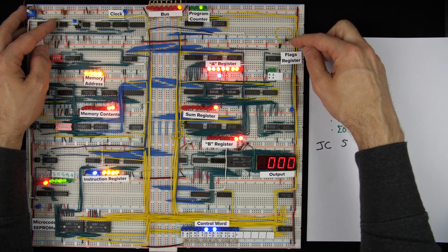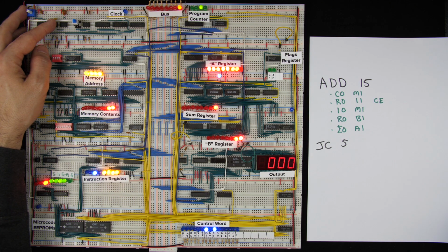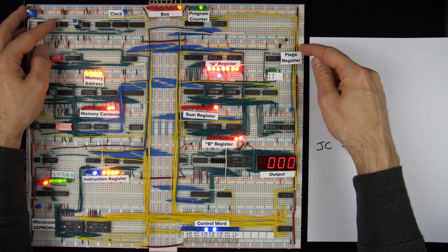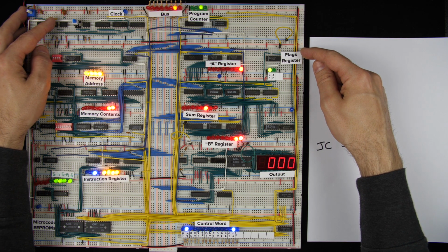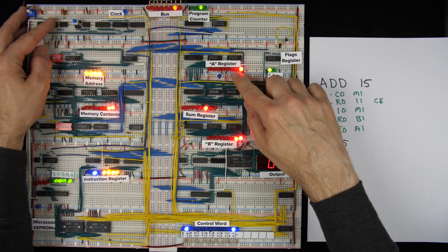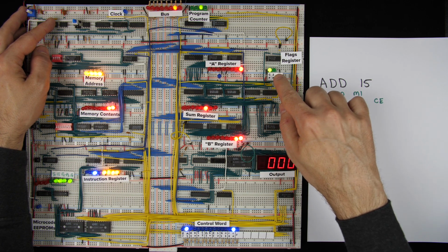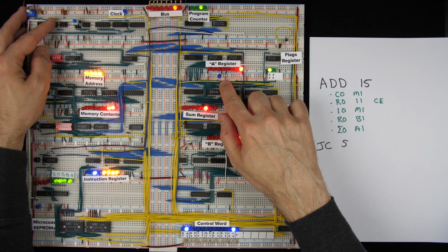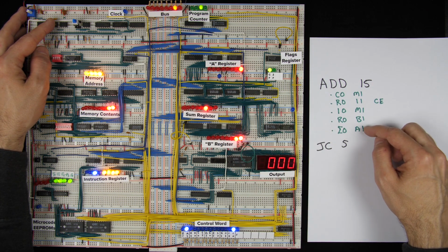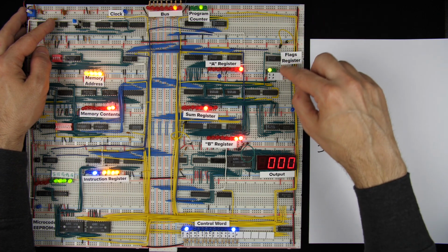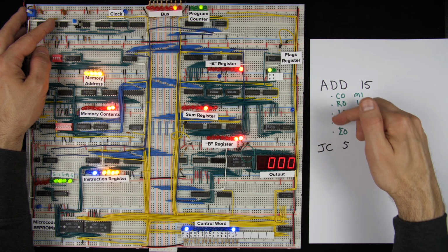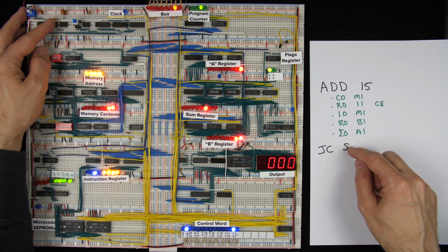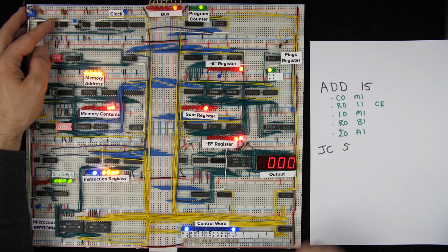So we'll set that. It's active low, so I'm setting it low. And then now I'll pulse the clock once more to execute the sum out, A in, flags in control bits. And okay, now we've got that. So we've got the answer, which was 1 in the A register. And now we've got the carry bit in the flags register, even though now the carry bit down here isn't set anymore. And so now that we've executed this last step of the add, we can disable the flags register again, and it'll hold on to these values. So if we continued running this hypothetical program, we'd have the information we need to know what to do with this jump carry instruction sitting right here in the flags register.